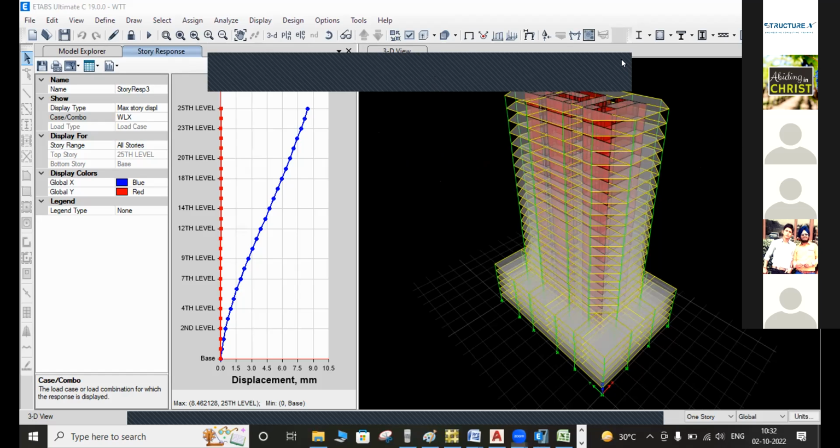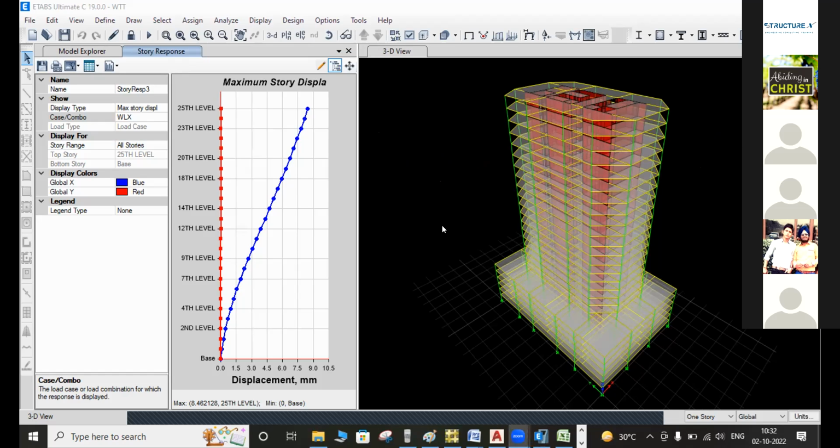So in that part, we have to interpret our results also. Is our lateral displacement not allowable? It's a high value. So it's under control. I think that is H by 500, which is a very large unit, but here we have a minimum amount, approximately between 7.5 and 9. So it's under control, right, Karim? Sir, what will happen if our displacement becomes higher? How can we control this?